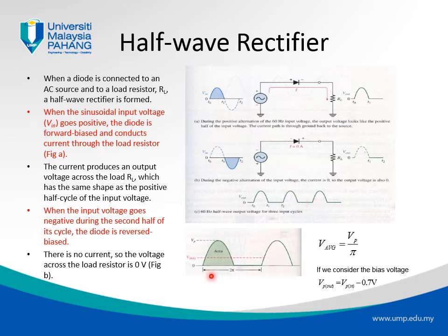For this kind of waveform, we can calculate an average voltage. The frequency is quite high, at 60 Hz or 50 Hz, so from the point of view of application, for example lighting applications, our lights can see only the average of the voltage. If you want to calculate the average of the voltage across the period of 2 pi, the average voltage is the maximum voltage, called Vp, divided by pi. That's the average voltage seen from the point of view of the load.